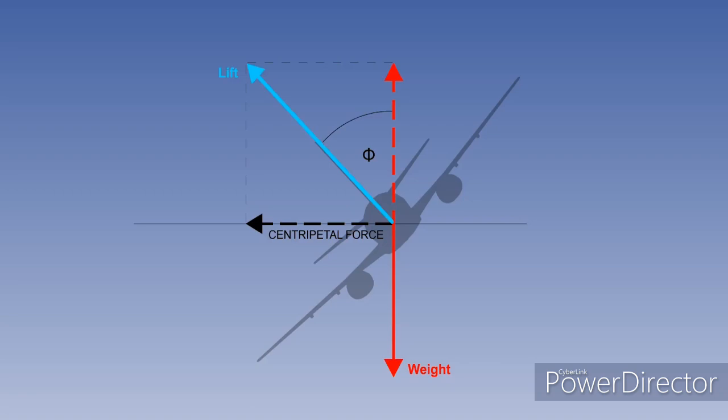However, not all aircraft can reach the same angle of bank at the same TAS. With a heavier aircraft, the vertical component of lift required increases, but the centripetal force necessary to maintain the same radius of turn also increases in the same proportion. The lift required, although greater, has the same inclination to the vertical as before, and the bank angle is the same.